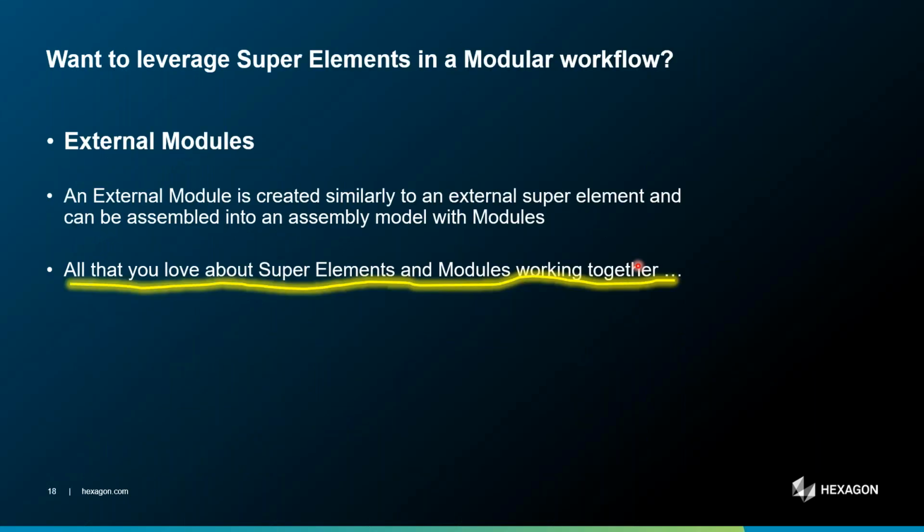So a question that might be in your mind right now is, I love to use super elements, Larry. Can I use super elements in a modular workflow? The answer is yes. It's called external modules, and an external module is created similar to an external super element and can be assembled into an assembly model that contains modules. So basically you get all that you love about super elements and all that you might love about modules working together.